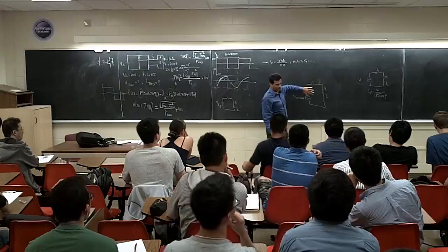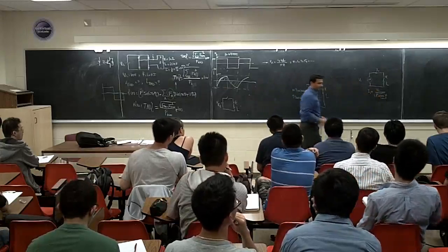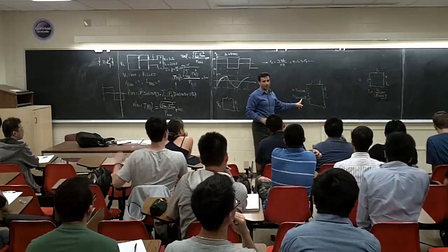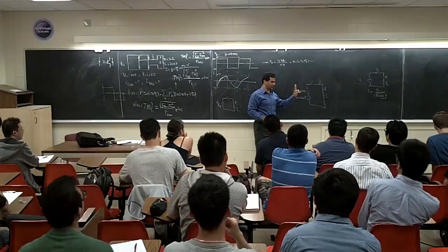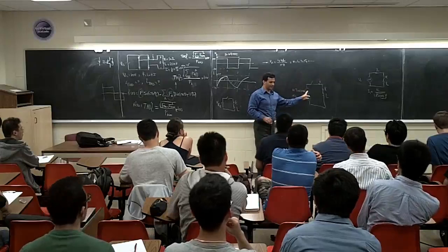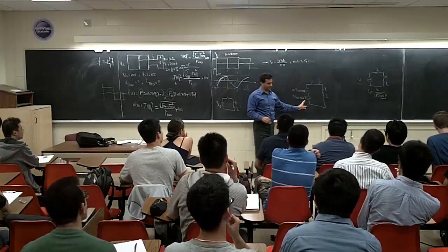Now I get rid of this one and I have this one, and when you calculate this, the frequency is 1000. So basically your current also has two components: something sine of 377t plus something sine of 1000t. That's the way you solve it.